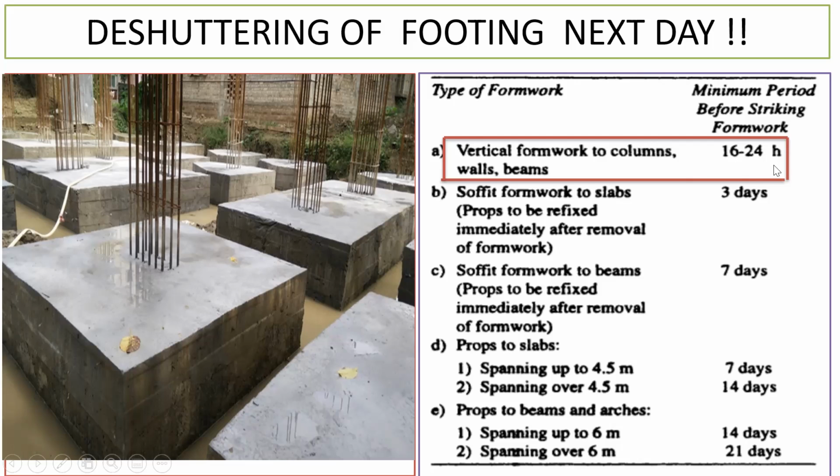It depends on how big the footing size is and what the depth of the footing is. If it is a small footing, like say 3 meter by 3 meter, we can take it off after 16-17 hours. It's always better to wait for a day. If you're casting around 12 o'clock in the morning, then the next day you can come in the morning and take it off around 11 o'clock. So you're keeping the shuttering for almost 23 hours. That's a good way to do.